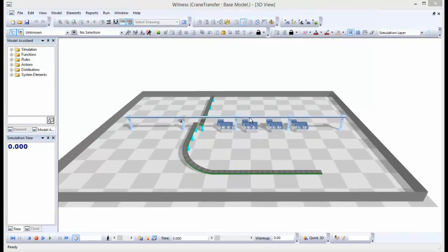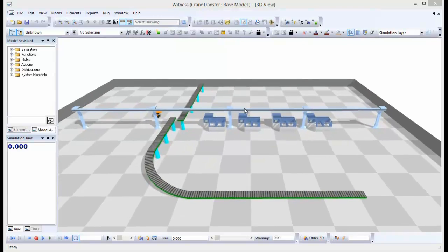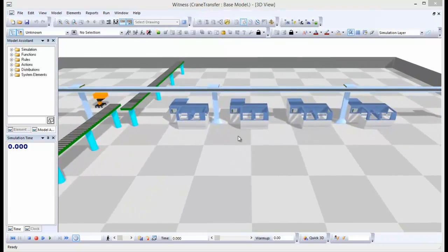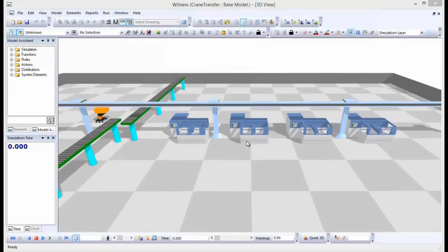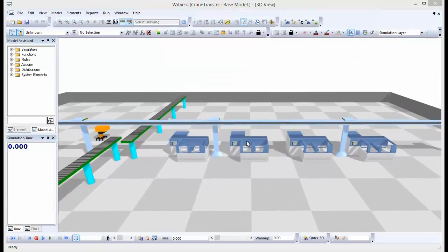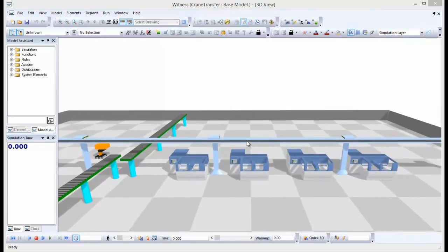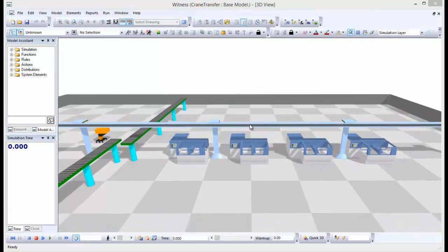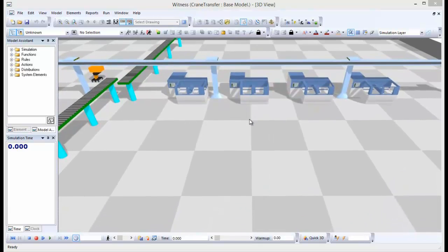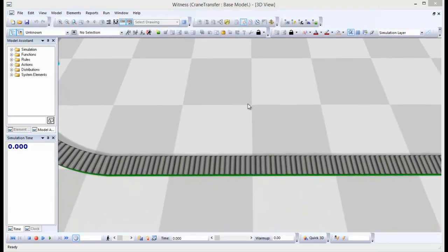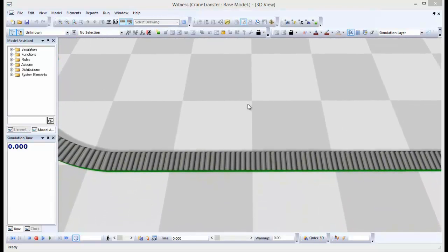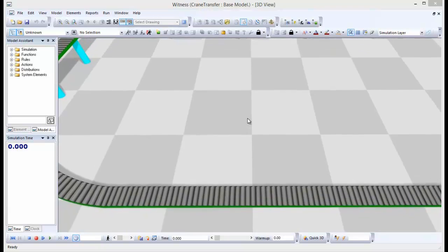The next command I would like to show you is using the Shift key. When we're at an angle such as this, if we hold the Shift key down and I drag the middle mouse key back towards me, the angle of elevation of the view goes upwards. If I move it in front of the middle of the screen, the angle of elevation of view goes downwards, so we can get a more vertical view of the 3D view that we have.